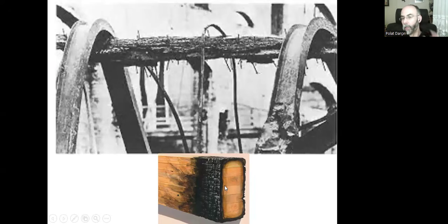And in normal conditions, the outer part of the timber will get burned, will turn into charcoal, and that thickness will provide sufficient heat insulation, and the fire cannot get to the inside layers. So the timber piece will be protected. It burns, but it can stand.